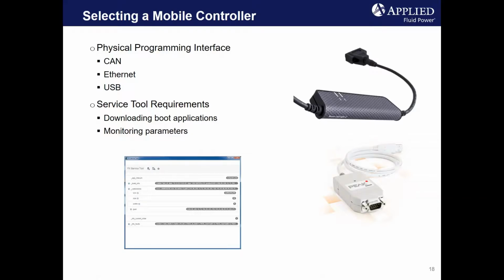Programming or program updates over a physical CAN interface can simplify things by just connecting to an already existing CAN network in the control system. However, CAN communication is slower than connecting to a controller via Ethernet or USB. The results are things like longer download times or slower update rate when online or viewing your code live on the controller.